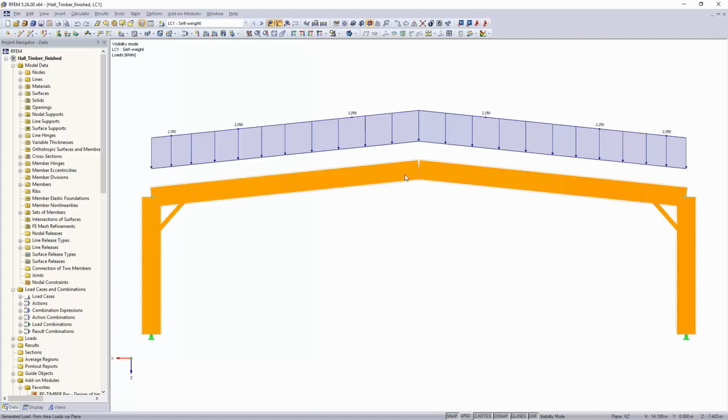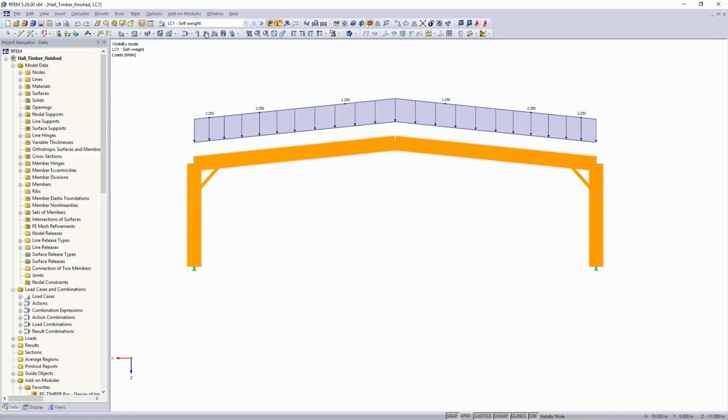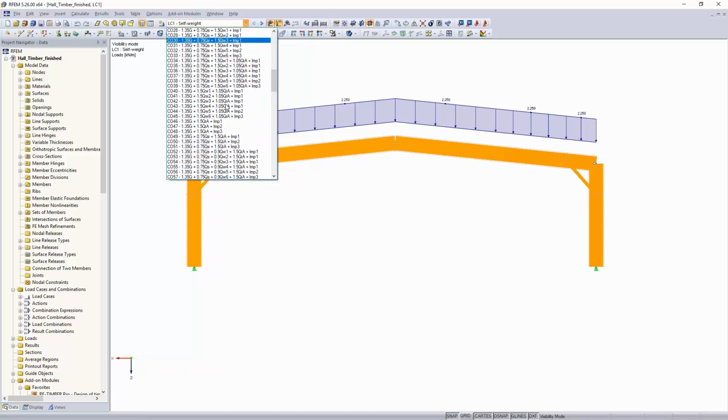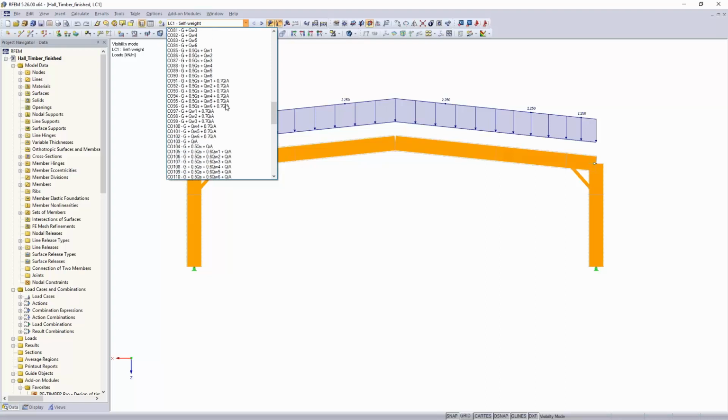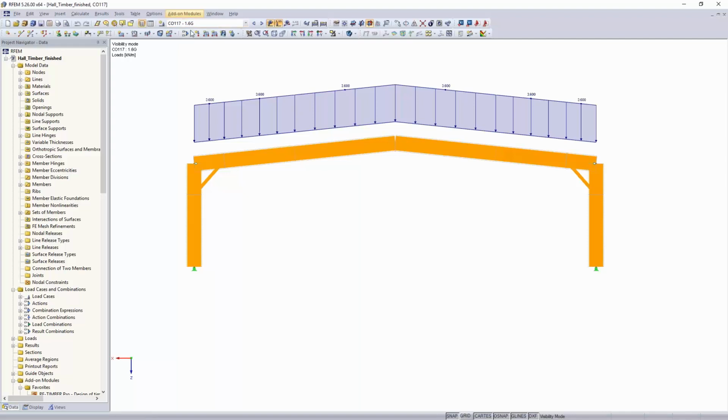Let's have a look at the serviceability limit state in combination 117. You see that in order to regard the creeping, the software increased the load by a factor of 1.6. Andreas mentioned that last week. Now, how could you do that in case this was a highly nonlinear system? Because then increasing the load will not regard creeping correctly. That would work by copying this and reducing the stiffness. That's just one way how you could do it.